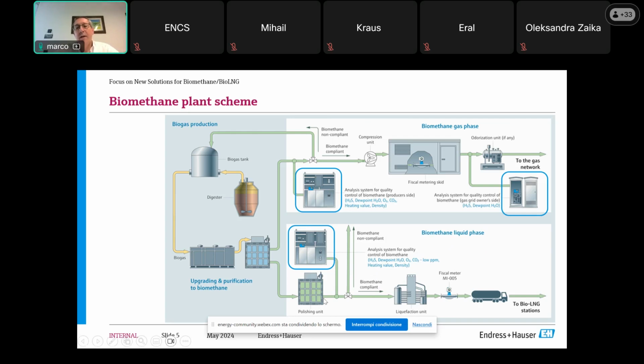And then I measure the CO2, and the laser TDLAS analyzer is the best way to measure a low concentration in a methane stream. Then I liquefy it, and my custody meter flow measurement is done immediately before the load of the produced liquefied biomethane to the tank.